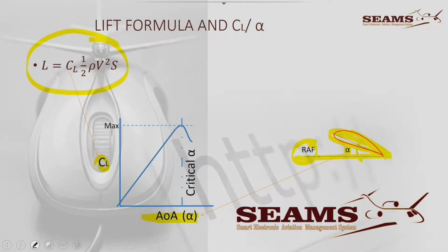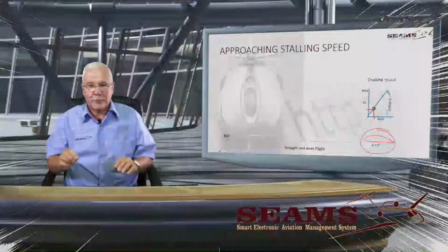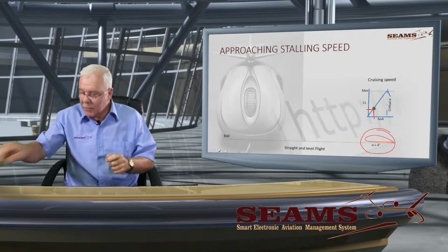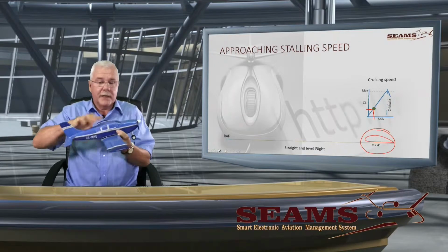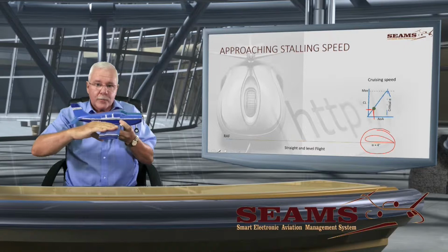All right, so if we now go to the next slide, let me just take that one out there and give me a little bit of a pen. All right, I started off with 4 degrees, and that's the angle of attack. Now, don't confuse this. The best lift-drag ratio happens at 4 degrees. It so happens that most aircraft, if the wing is so designed, will have an angle of incidence. That is the angle at which the wing is attached to the longitudinal axis. It's got like a 4 degrees.